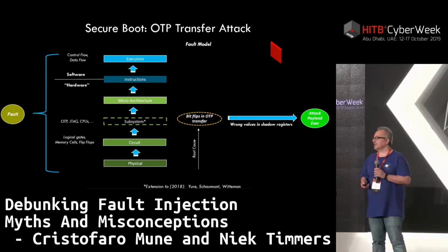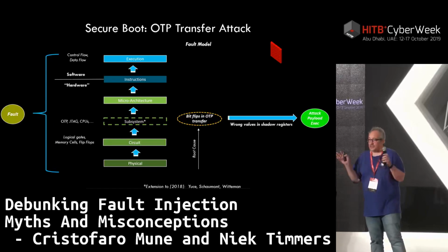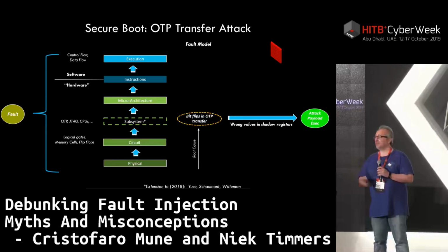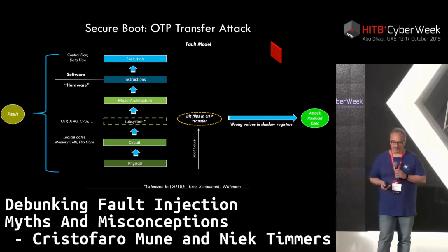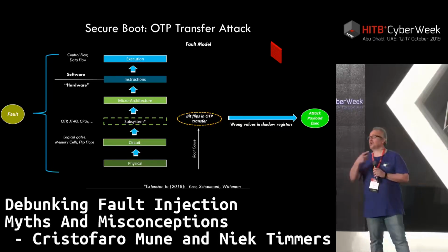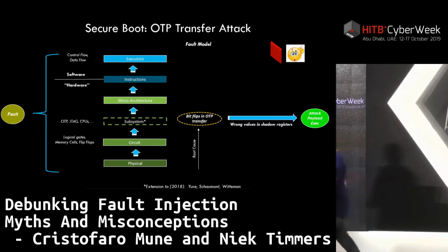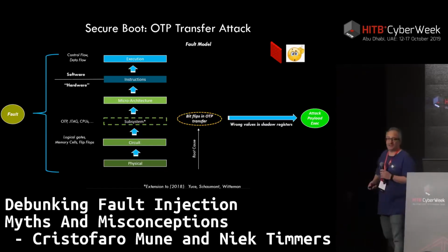So this means that the CPU says, okay, secure boot is not enabled, and it will continue executing your malicious code because the check is not being done, because the setting has been presented to the CPU as not existing. So we are not even going after the instruction. We are attacking the subsystem, but the effect is the same. Your software countermeasures will never trigger because they should not even be used in the first place.